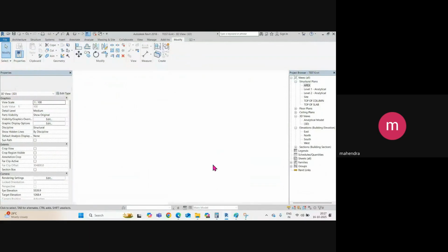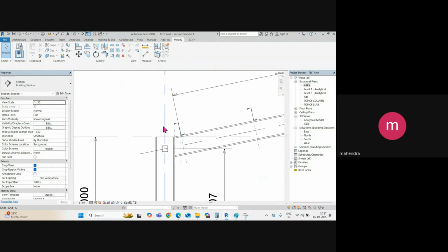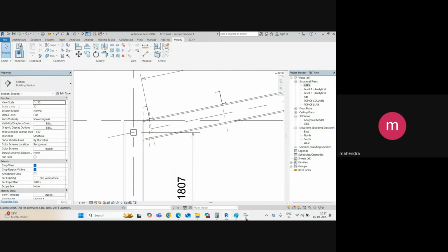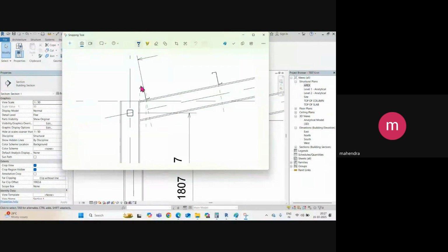Then after that, metal sheet will come over here, right? So for example, I will take again a snap. So our metal sheet is like that, and then they will just screw it like that. And then what about here? Okay, so you need to add the end purlin here. So mostly we are using the end purlin as C channel or C shape purlins like that. And then your sheeting looks like this. Then this end purlin should be here like that.